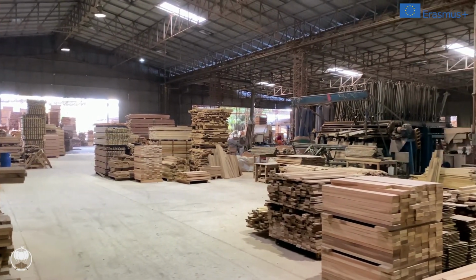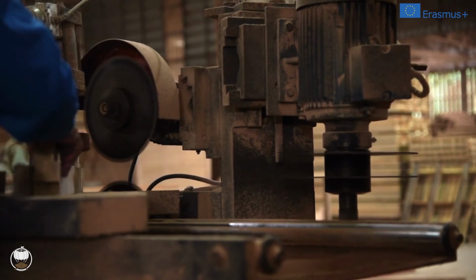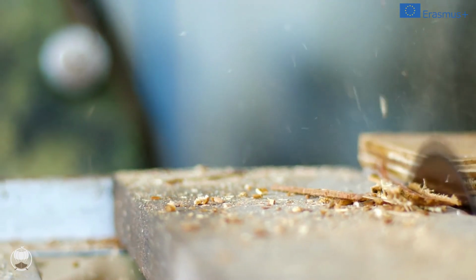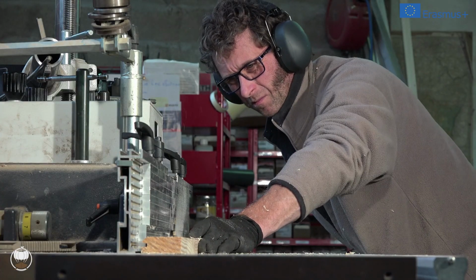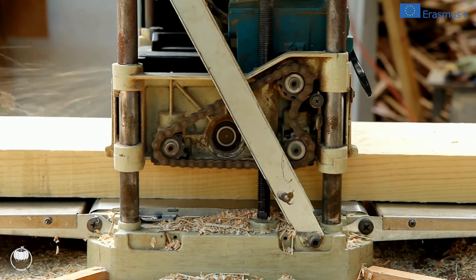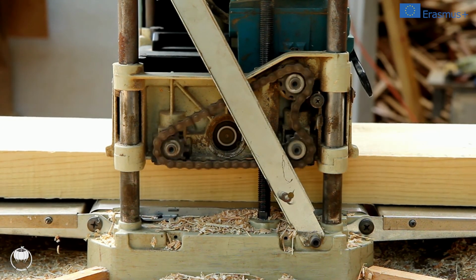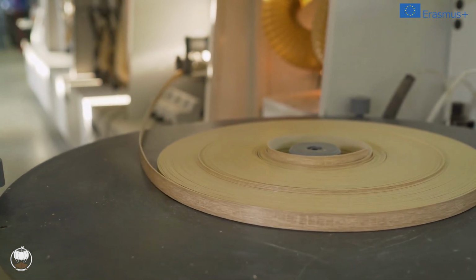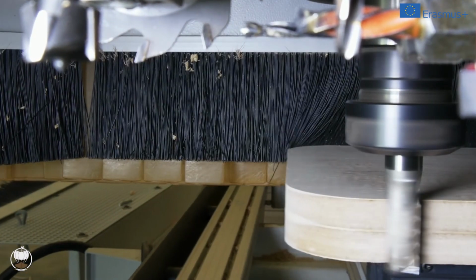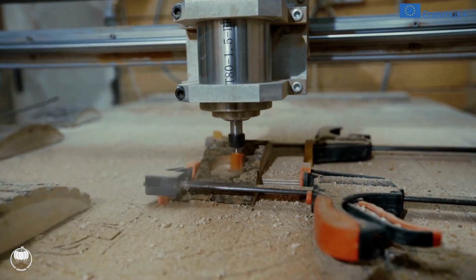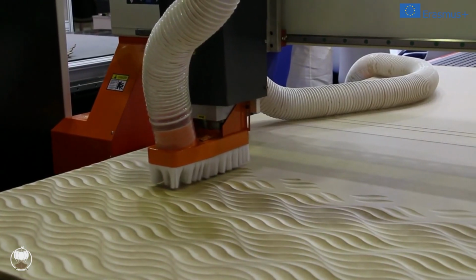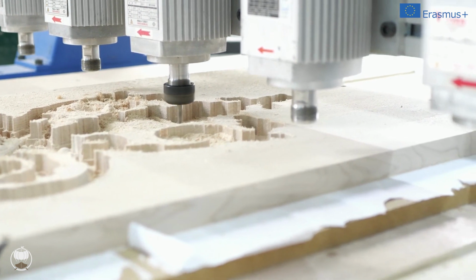After the initial sawing and already in the factory, the wood is further processed. Custom cuts, planing, thicknessing, etc. Within these systems, we find spindle molders for molding and grooving, molders combining the planing and thicknessing processes, edge banders for the banding of board and panel edges, linear edge milling machines for curved parts, and the most advanced CNC machining centers capable of performing various tasks such as drilling, moldings, cuts, and so on.